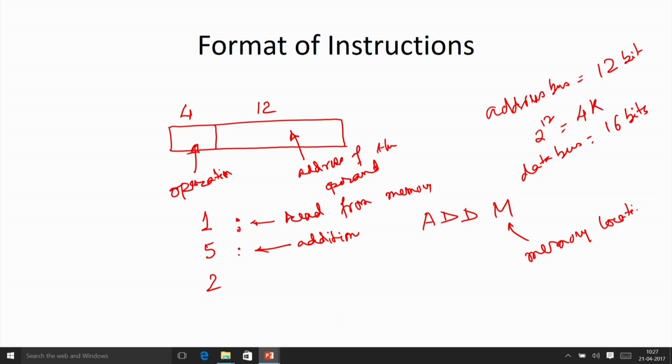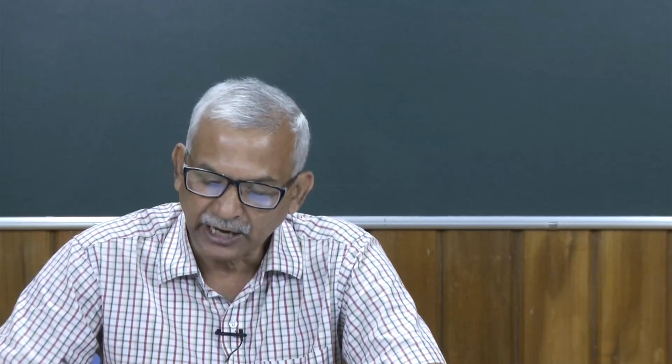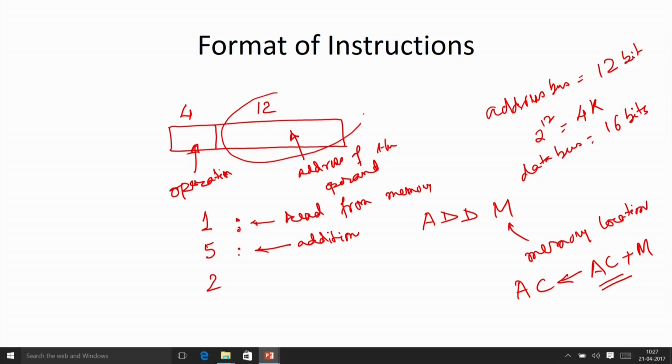So, we are giving the address of a memory location. We are going to take the information from that particular memory location and add it to the accumulator, and store the result in the accumulator. So, the effect is: accumulator = accumulator + contents of this particular memory location. The second operand is my implicit reference. We need not mention it categorically; we always take one operand from the accumulator and the second operand from the reference we give along with this particular instruction.